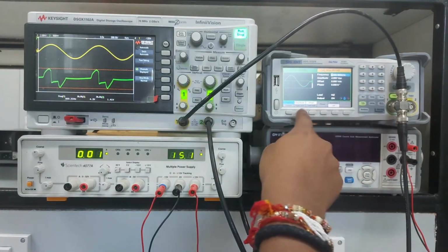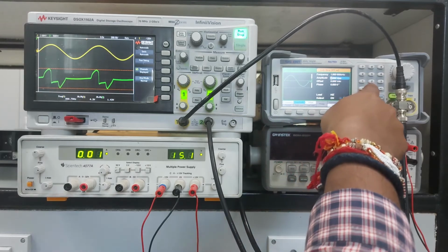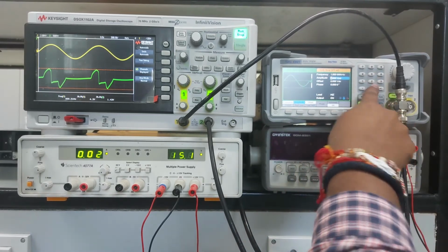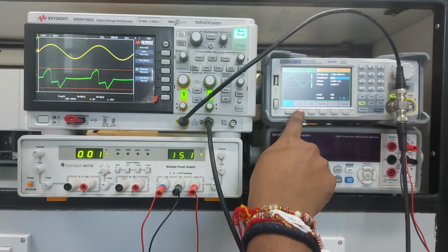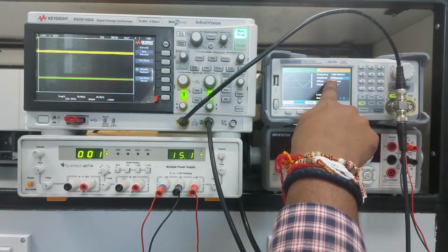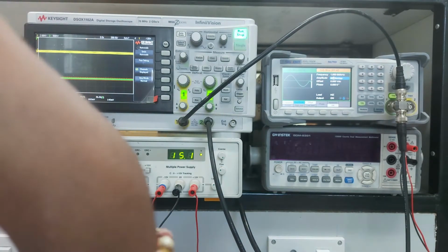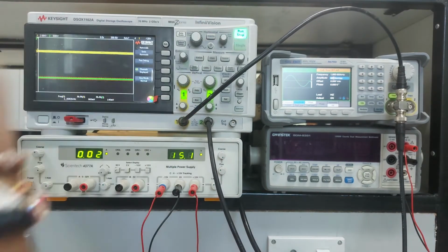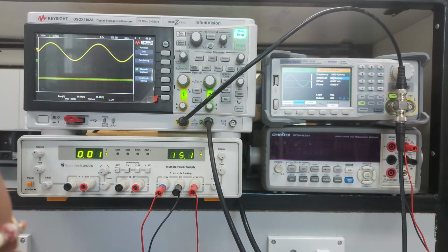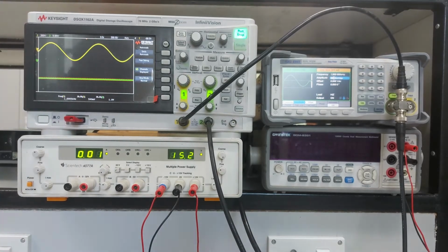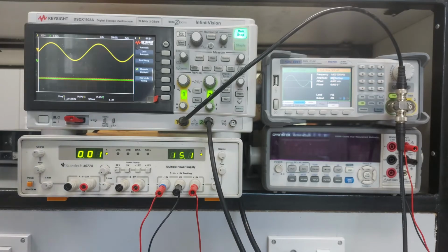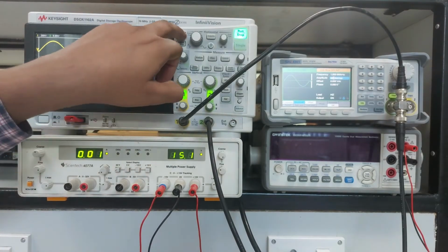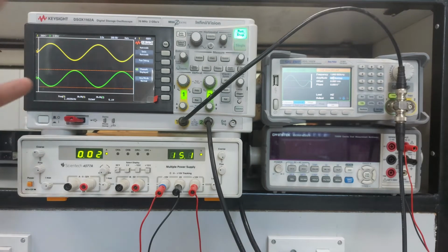Okay, so I'm going to reduce the amplitude of the input signal. Right now it is 4 volt, so I'm going to fix it at 500 millivolt or 0.5 volt. See, right now it is 500 millivolt and frequency is 1 kilohertz. So again I am going to auto scale it. Okay, so we are getting nothing actually, right? Sorry, the connection was a little loose, that is why it is fluctuating. Again, yes, now here you can see